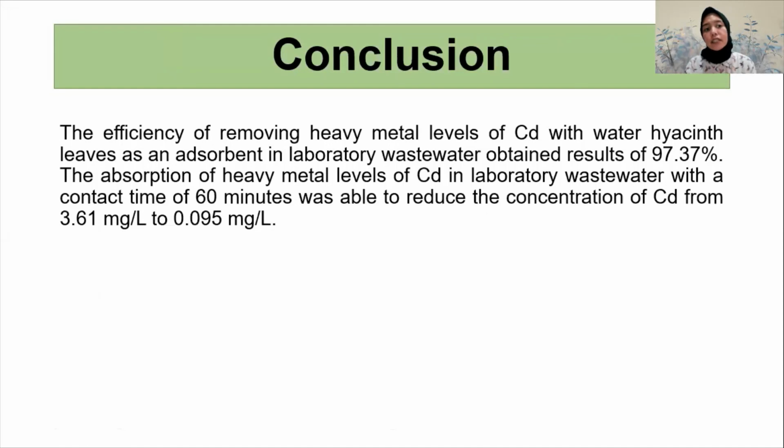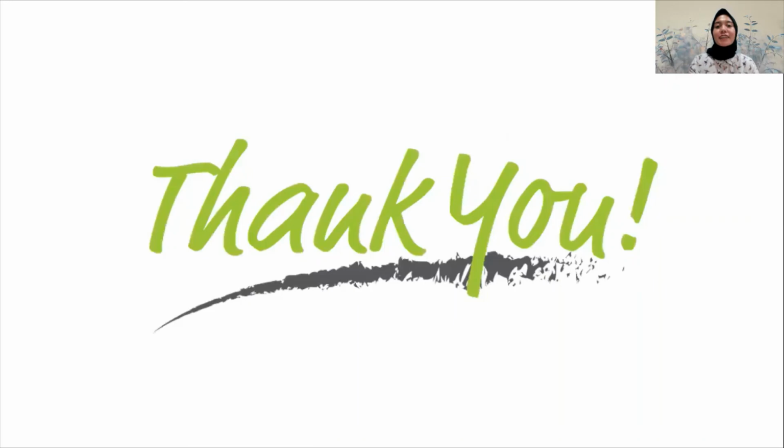And the conclusion is that the efficiency of removing heavy metal Cd with water hyacinth leaves as an adsorbent in laboratory wastewater has a result of 97.37%, and the adsorption of heavy metal Cd in laboratory wastewater with a contact time of 60 minutes was able to reduce the concentration of Cd from 3.61 milligram to 0.095 milligram. Thank you for your attention.